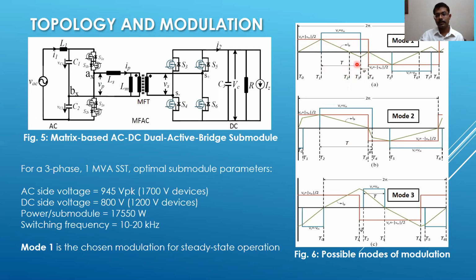So basically this T is being modulated sinusoidally, and it gets its pulse width from the sinusoidal modulation scheme, or the sinusoidal modulation index, I would say. And the phi is being controlled using the control system, or even if it is in open loop, we give a constant phi, or a pre-designed phi, so that we can have the desired power transfer.